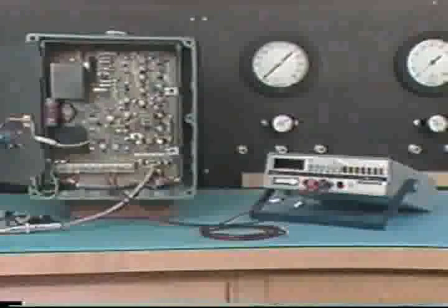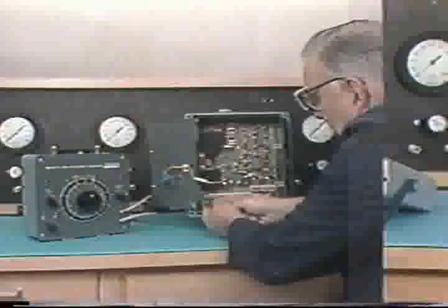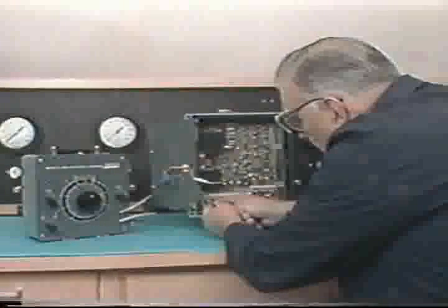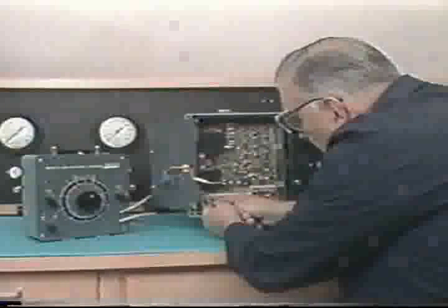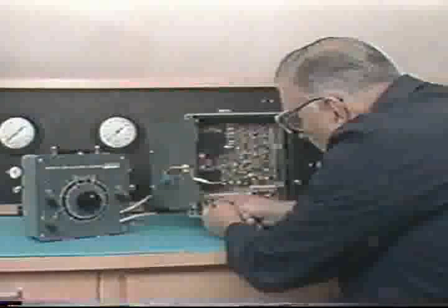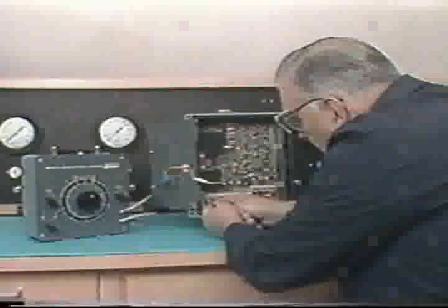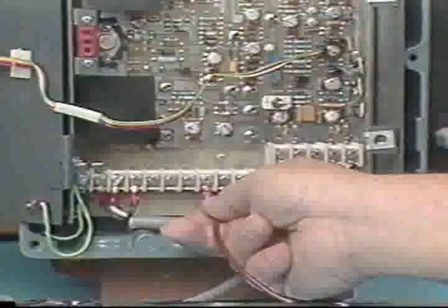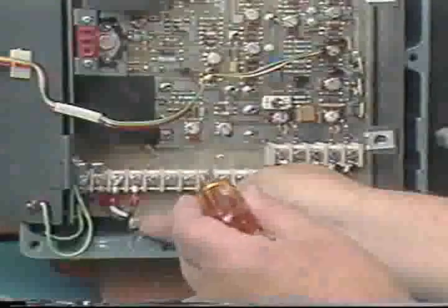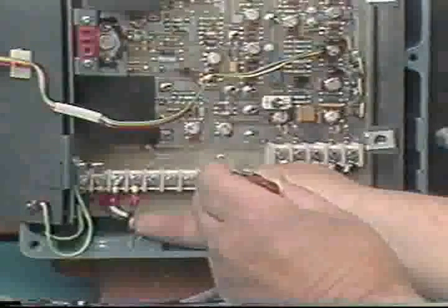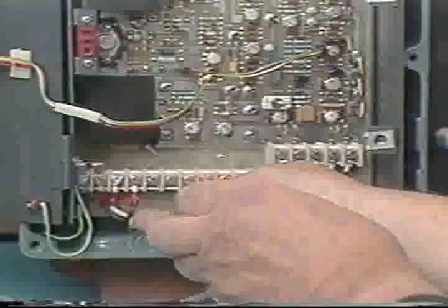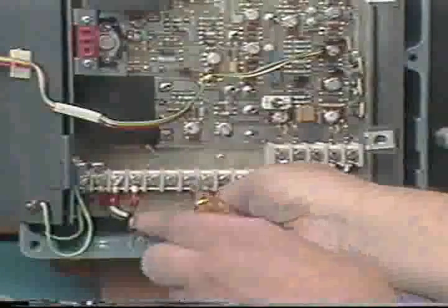Since output is provided in milliamps, a milliamp meter is the appropriate output standard for this calibration setup. The power supply to the transmitter is 110 volts AC. Power to the calibrator is provided by the transmitter. The signal source from the calibrator is connected to the transmitter. The signal out of the transmitter is taken from the DC out terminals and is connected to the milliamp meter. It's important to observe the proper polarity when making this connection.